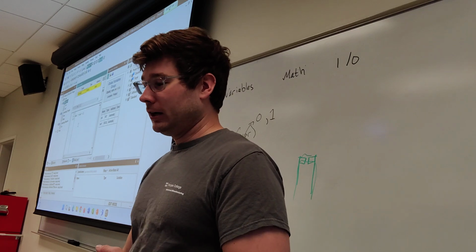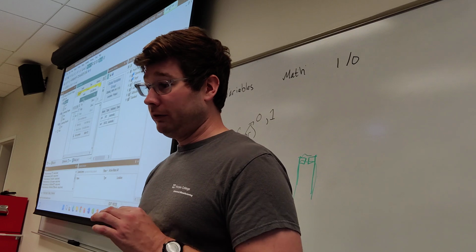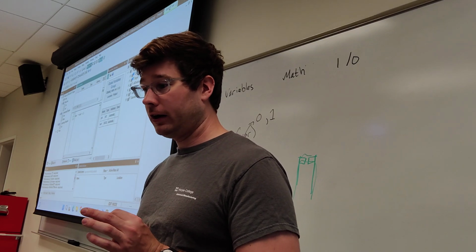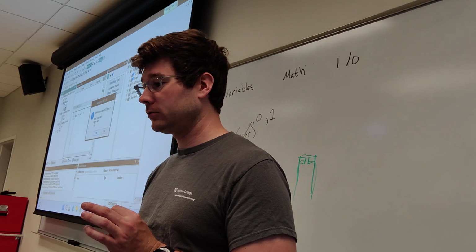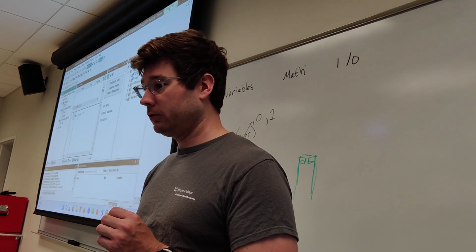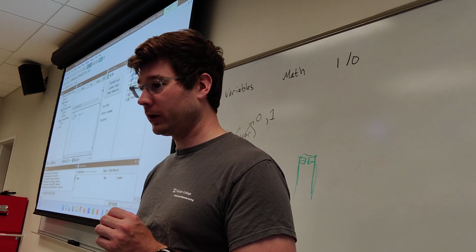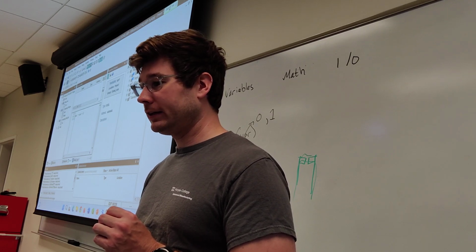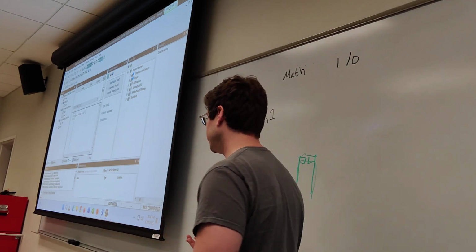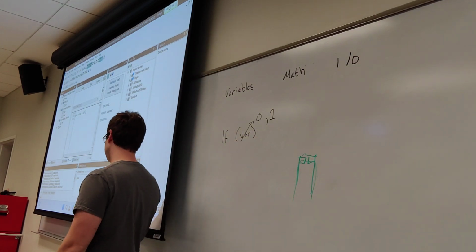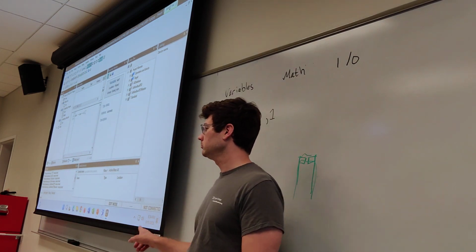All right. I want you guys to delete any variables that you made. We're just using the global variable count. Here we can right-click and delete variables. We're just going to have count. You can have ham or whatever, it doesn't matter. So we're going to connect if you haven't already, and then download PLC code. And then it'll push the code. You should see 2 green blocks in the bottom right.